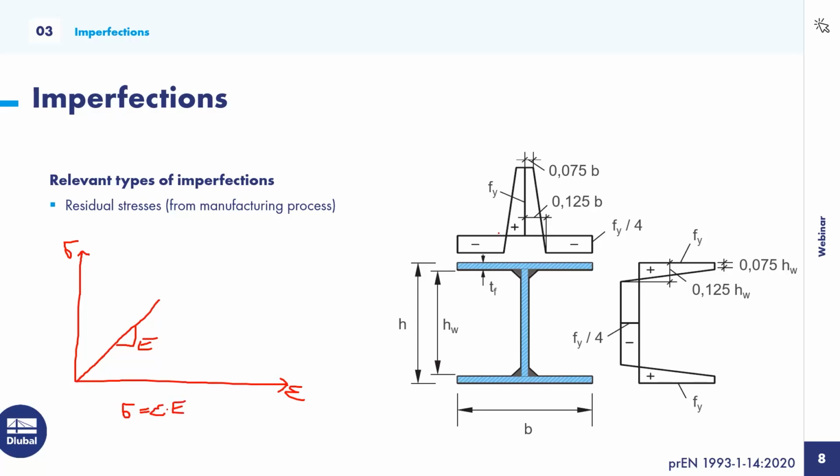And since we know the stress that we need to apply, it is given in the Eurocode, like we need in the tension sections stress as high as the yield strength, and then in the compression parts, a fourth of this, we can compute back the required axial strain that we need to define in RFEM. Then secondly, in RFEM, we can only define a constant strain state or a linear strain state. But we have some progress of this curve over the flange that cannot be described by one of those definitions.